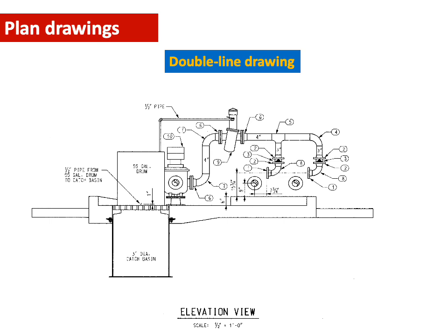here is going to be an example for the double lines. So you can see, right, it's more like an orthographic view, and you can have a similarity in comparison with the general drawings. So double lines is much more to represent each part. It can't be drawn like a full plan because it's going to be much more crowded with too many details. So by having single lines, it's much preferable for a piping drawing of the whole factory, bigger and more complex.